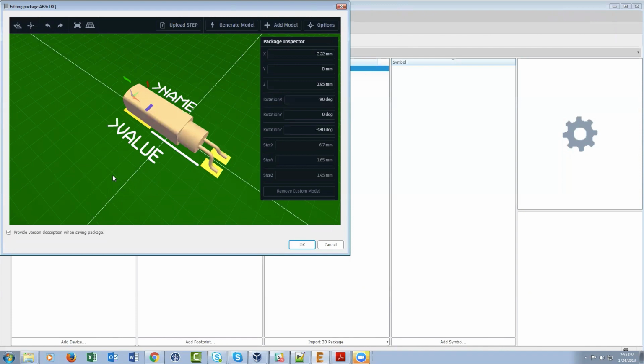Hey, Chris, yeah, you are correct. If you have large components, it does get a little complicated. That's why we have the pad array and the pin array. We also have something called make package symbol and device, which creates components as well, for more complicated components. But the package generator really solves a good portion of components, and that's why we have it.